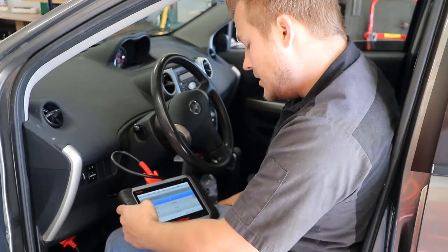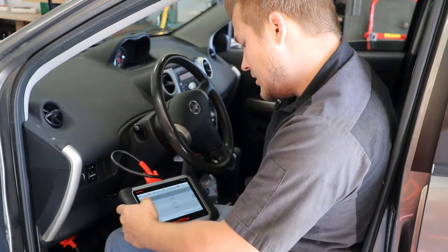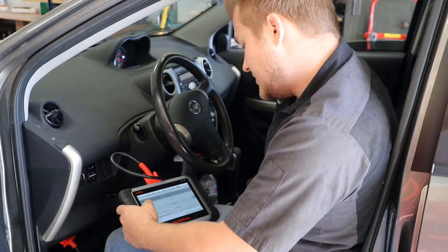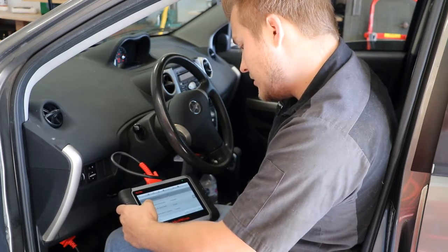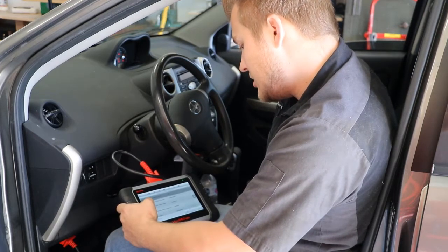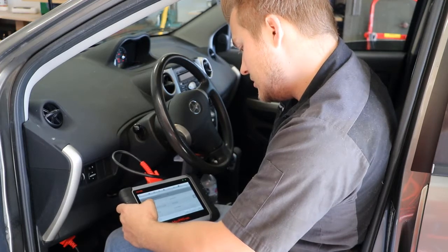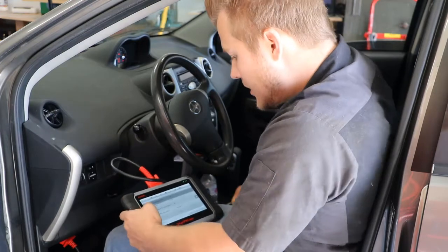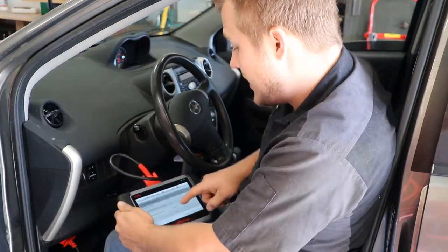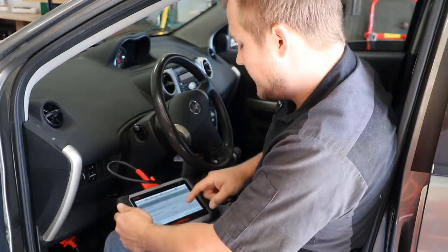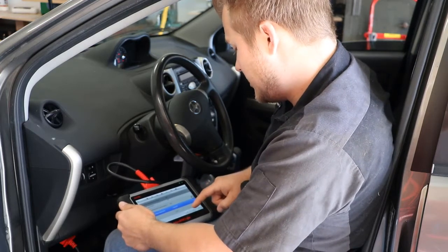There we go. MIL status is on. Complete parts monitor is available. Fuel system monitor. Continue that. Misfire monitor. The EGR is off. Sensor. The purge vacuum switch valve is right now currently closed and off. So I was looking for that switch really quick. So let's go here and let's go ahead and click it on.